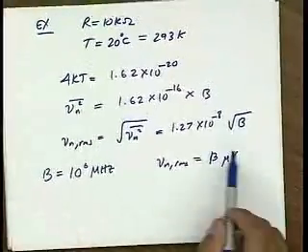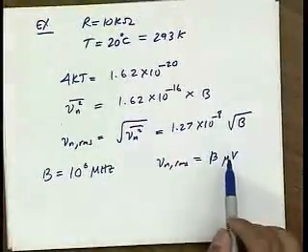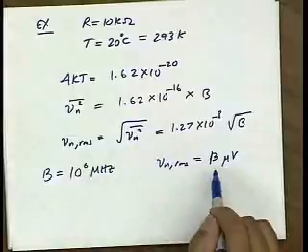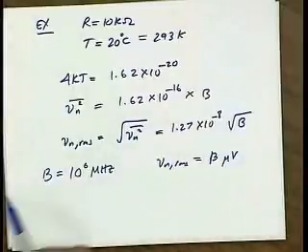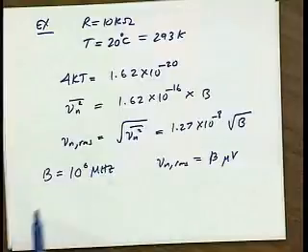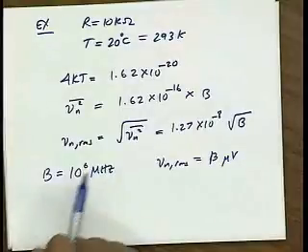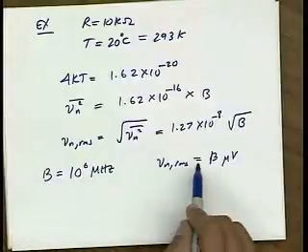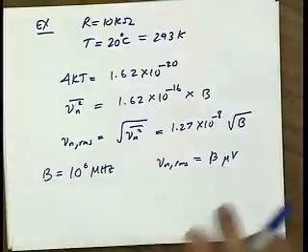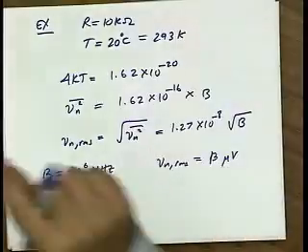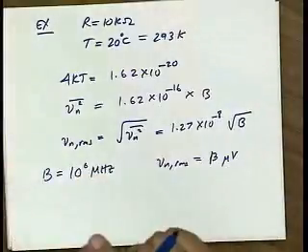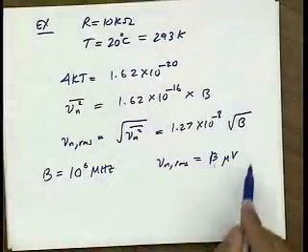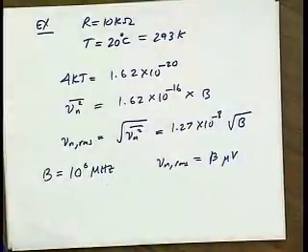So this is actually a large enough value that you can even observe it on a scope. If you go on an oscilloscope and you put a resistor across it and make sure you're in a high input impedance mode and limit the input bandwidth, let's say it's a scope that has a natural bandwidth of about a megahertz, then you will see roughly a thick line that represents the noisy voltage, and its thickness will be roughly on the order of 10 microvolts or so.